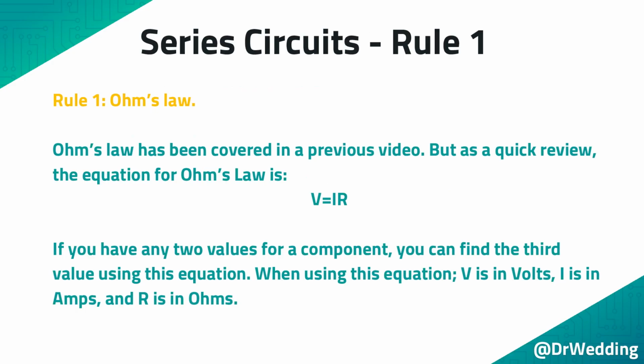Rule 1. Ohm's Law. Ohm's law has been covered in a previous video, but as a quick review, the equation for Ohm's law is V equals IR. If you have any 2 values for a component, you can find the third value using this equation. When using this equation, V is in volts, I is in amps, and R is in ohms.